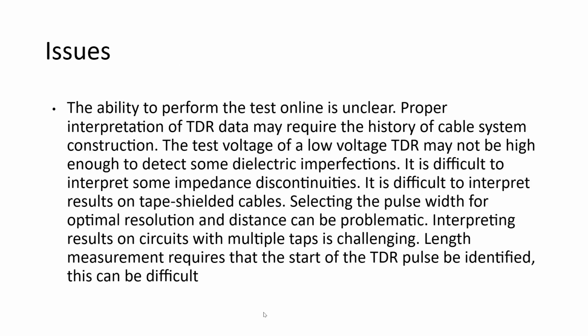Then, on the issues: the ability to perform the test online is unclear. Of course, in our lab we are developing a technique to conduct this test online also, and we have succeeded to some extent, and the research is still going on in our lab. Proper interpretation of TDR data may require the history of cable system construction. The test voltage of a low voltage TDR may not be high enough to detect some dielectric imperfections.